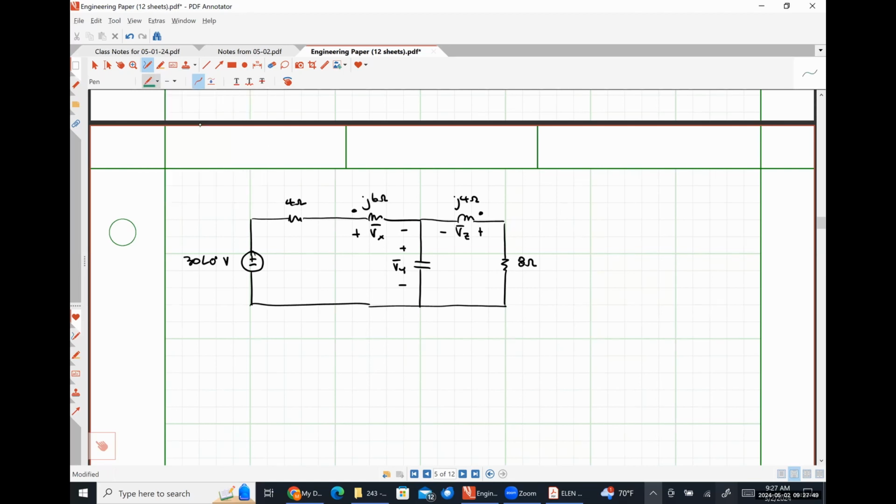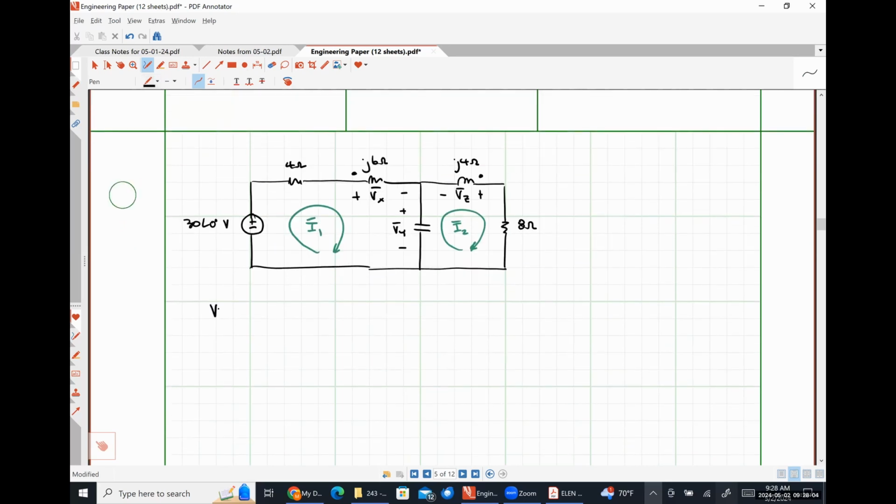Clockwise, okay? And then Baylor said clockwise for both. Perfectly reasonable. All right. So let's sort out the voltage Vx. Okay, so that is the voltage drop across one of our coils. Oh, and to be clear here, we have J2 ohms of mutual inductance impedance between our coil X and our coil Z, as it were.